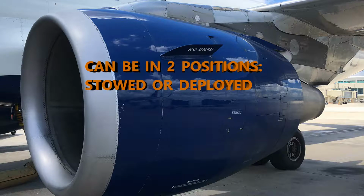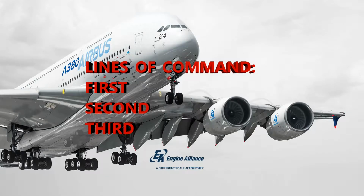The lines of command, there's different kinds. When the pilot is deciding to execute the thrust reverser position from stowed to deployed, there's going to be signals generated going to the primary and secondary computers. The signals are coming from the potentiometers as well as the signals from a radio altimeter system. So those are the two places where signals are coming from and going to the primary computers.